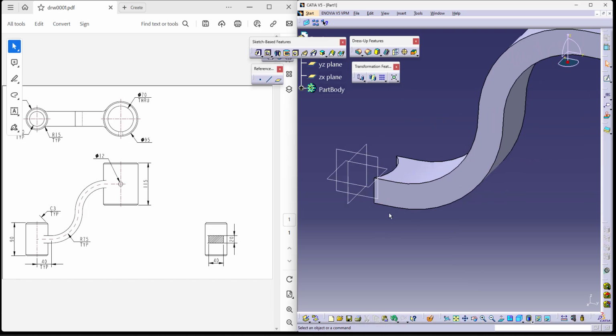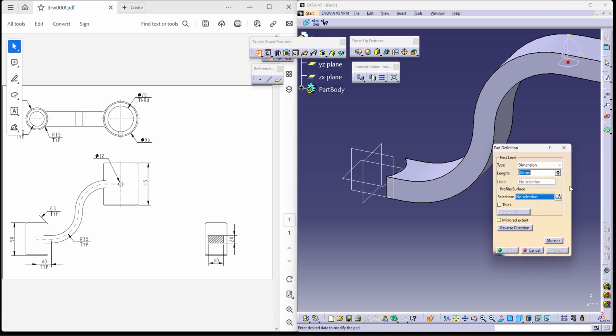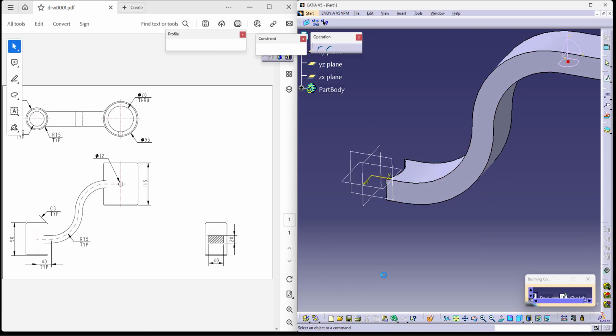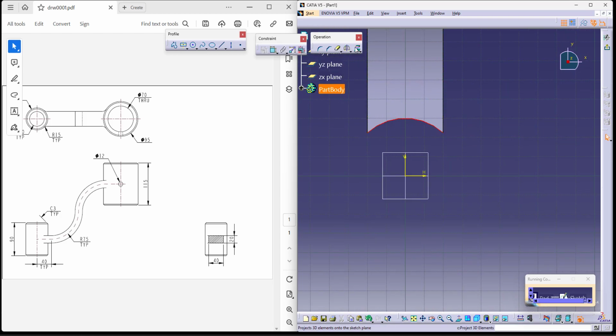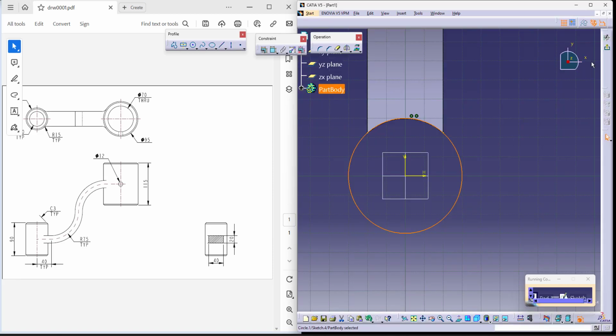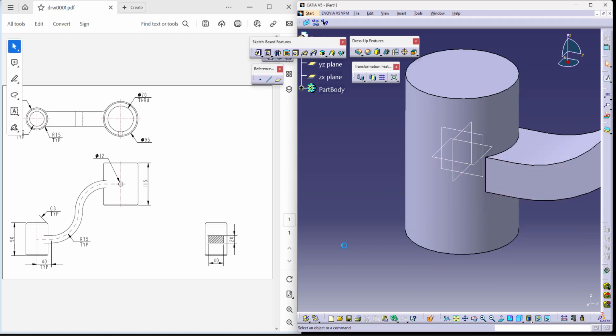Now let's add the material. By leaving that portion, you cannot get the cylinder and weld it. It's not practically possible if you're working in a manufacturing place. Hence, you usually cut this shape and then start welding. Then let's take a circle of the same size, because I've already given the dimensions. We know the addition of material is up to 90 in total, so I'm just using mirrored extent and giving 45 on either side.